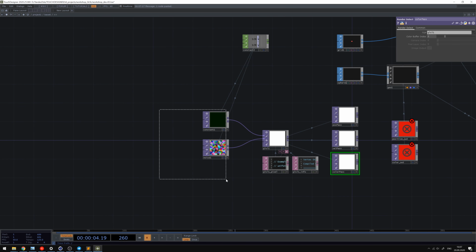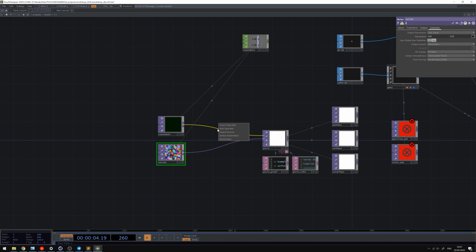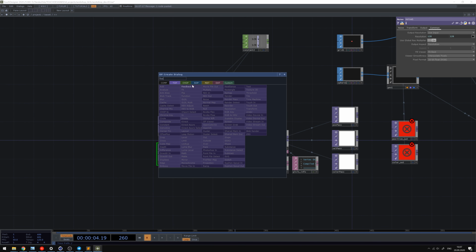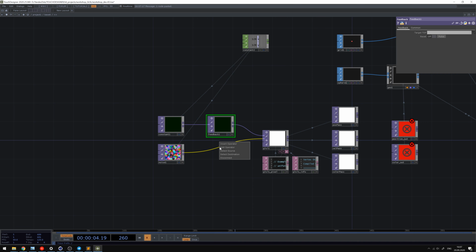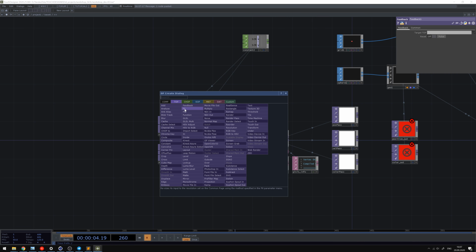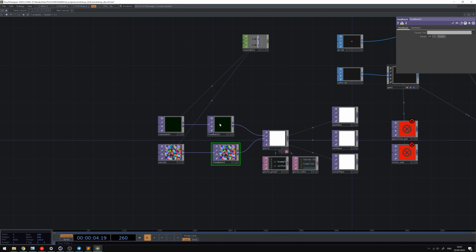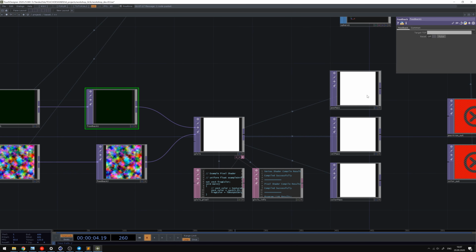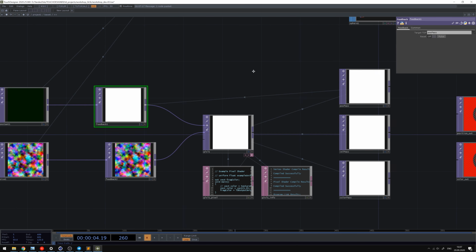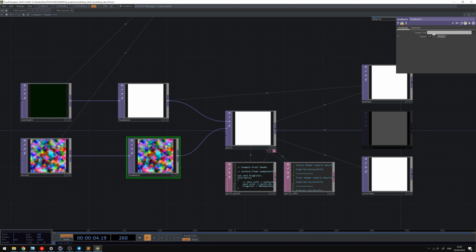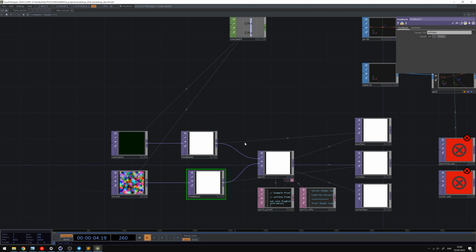Let's add feedbacks before our input in GLSL, and in the first feedback, let's set our target TOP to position pass. In the second feedback, let's set velocity pass as input. And now we have 2 loops that go through our GLSL node.